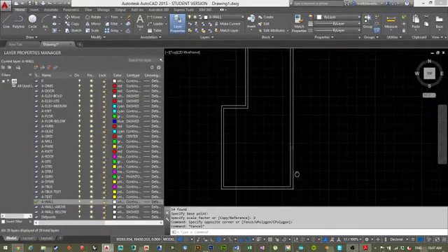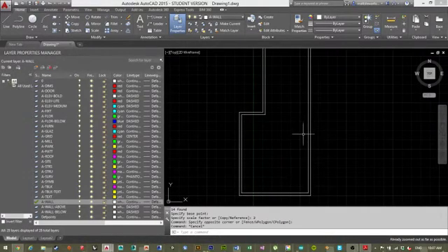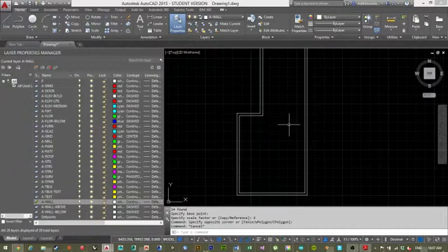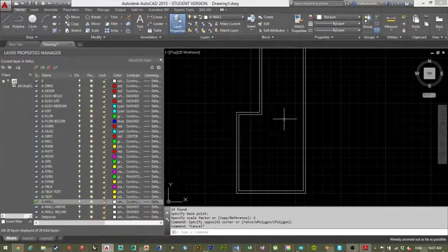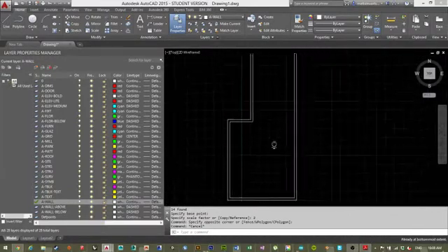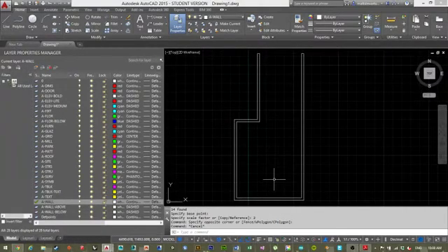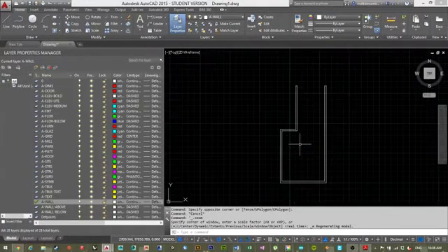But this is actually going to be a good point to show something. Right now it won't let me zoom out anymore. You'll probably come across this pretty soon once you start doing it, where I can zoom in, but I can't zoom out anymore. What AutoCAD does to save memory is that whatever you're looking at, it puts into memory, and the rest it forgets about. So right now it's not thinking about anything outside of this anymore, so it won't let me zoom out. But at least on Windows, if I double click, it resets.